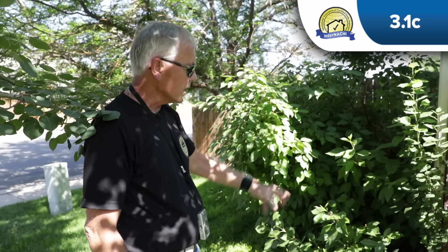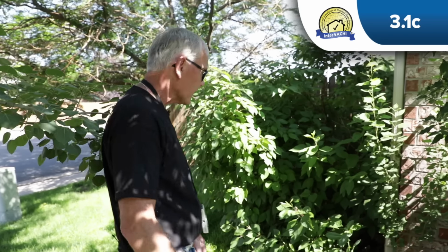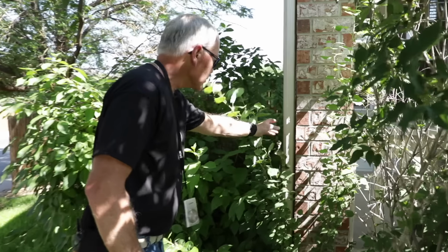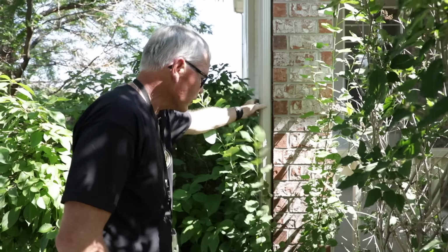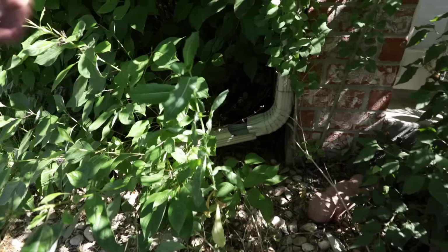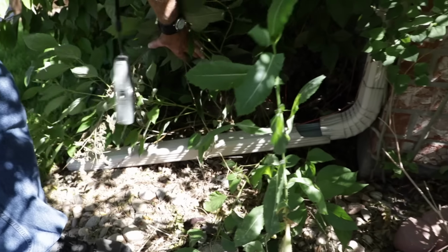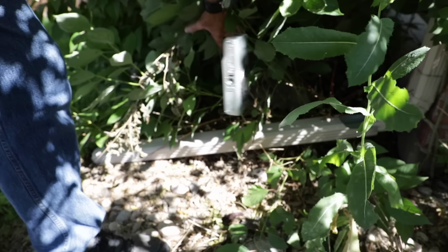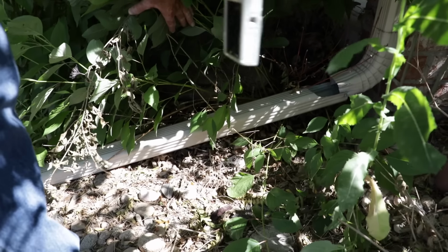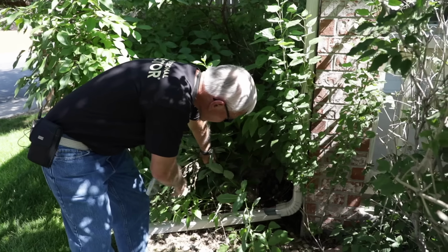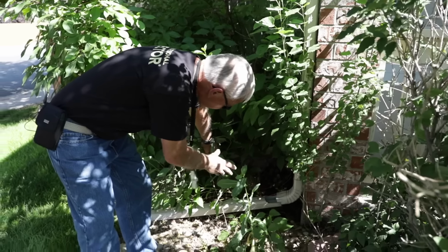We're going to move on to the roofing downspouts now. And the first thing I like to do is just make sure that our downspouts are secure to the house. And then I'll go down here and look and see if we have at least a 4 foot to 6 foot downspout extension. I always like to check these for damage or debris that might be clogging up the downspout. If there is any damage or any kind of debris in here, that really can affect the way the rain gutters handle the extra water.